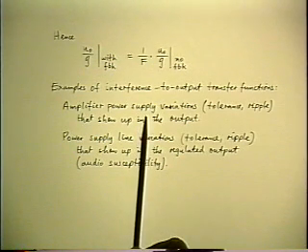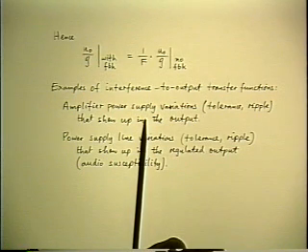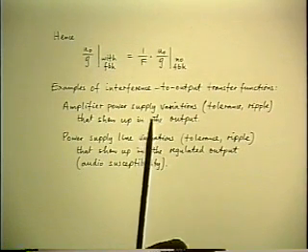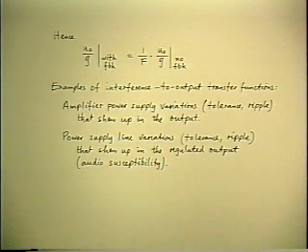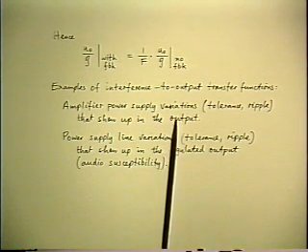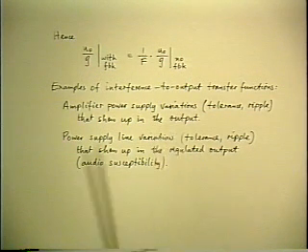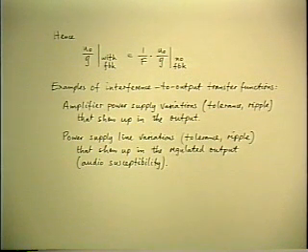The interpretation of the interference signal is where this becomes useful, and it has lots of interpretations. One of them is that the interference may be power supply ripple. It's just another input that comes in part way down the amplifier's string. It may also be thermal noise, which mostly comes in the first stage.